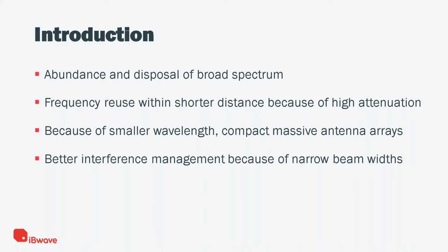There is a maximum of 5 carrier aggregation that can be applied in 4G. So 5 carriers with 20 megahertz each will end up with a total of 100 megahertz of channel bandwidth. However, in practice, not all operators would have these 5 channels of 20 megahertz. We may have maybe 3 or up to 4 channels, which is a maximum of 60 or 80 megahertz.